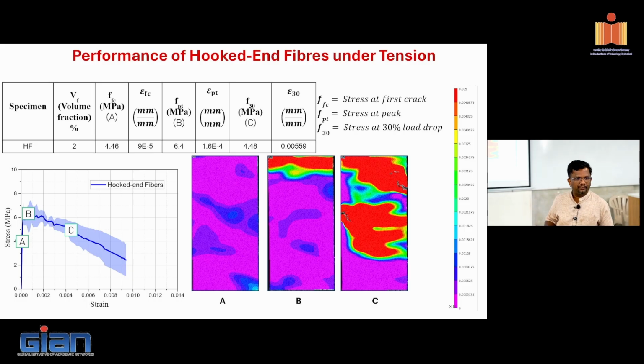Sometimes if you have higher energy, your machine is also not able to control that. It is fading suddenly, so the energy dissipation is also very high. That point is well taken. But it doesn't remain flat and then fall suddenly. It reduces, and then there's something called strain localization. After so much cracking, it will become unstable and then it will give way. But that flat portion was an idealization.